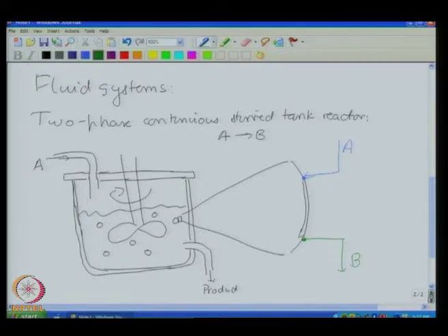Okay. So, A comes to the surface, the reaction takes place at the surface, and then the product B comes out. It is also necessary to ensure that the product B comes from the catalyst surface back into the fluid at a sufficiently fast rate, because if the B does not come out of the catalyst surface and it just sits there, there is going to be no place for more A to come back on the surface.